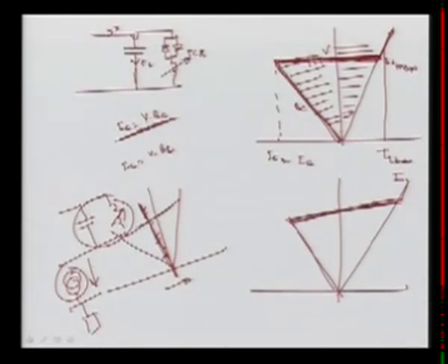But sometimes we have to go for another characteristic, where we intentionally provide more slope, for the loading of the line. With the regulation slope, the terminal voltage is allowed to be less in the capacitive zone and more in the inductive zone, because where we require more voltage, we have to go for this. Perfect regulation may result in oscillation, as I said. It is a perfect regulation here, and then it will be oscillating, due to the poorly defined operating point, that is, zero regulation. So here the operating point is not defined.